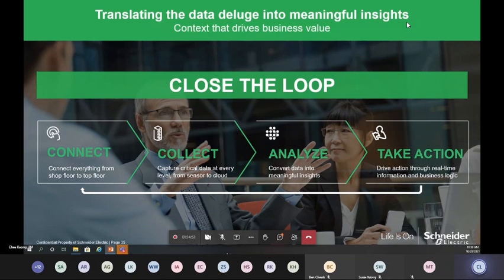I have come across a few times a question that tells me, so CK, when we put in analytics, when we put in advice, the system will be able to do the corrective action. Now here I would like to really put in a caveat. From Schneider's perspective, when we talk about correction, we talk about operational correction. So in other words, it's like set point adjustment, those operational issues.